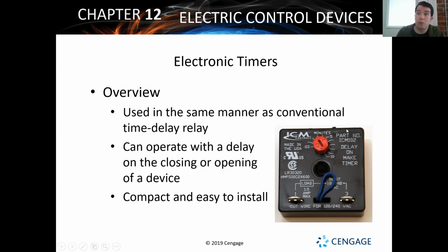And a customer will notice at that point, if they have a system that's short cycling, another thing they're going to see typically, not all the time, is the system will also cut itself off on high amperage sometimes. And this is something where the customer doesn't call in because the system's short cycling. They call in because it's not running enough. It'll run for a minute, cut off, stay off for 5 minutes, 10 minutes, whatever the delay's set to, and then come back on, but only for a couple of minutes.